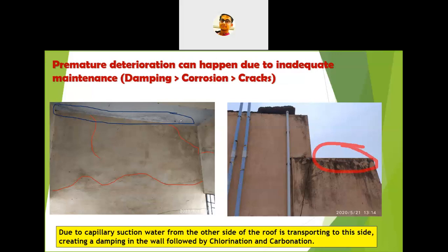and you can see here on the left side the dampness. And when the dampness happens with significant corrosion, cracks also form. You can see how the cracks are forming. I have given some red markings. In the entire wall you can see there is a huge crack. So very soon this concrete surface, this is actually an RC wall, will suffer from corrosion, and it's quite obvious.